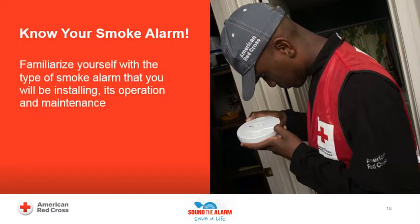It is important to take time to familiarize yourself with the type of smoke alarm that you will be installing, its operation, and maintenance before conducting the in-home visit. The Red Cross primarily uses 10-year smoke alarms. However, some locations may be using 9-volt smoke alarms. 10-year smoke alarms should be tested monthly and replaced every 10 years or earlier if needed. 9-volt smoke alarms should be tested monthly and have their batteries replaced at least once a year or earlier if needed.